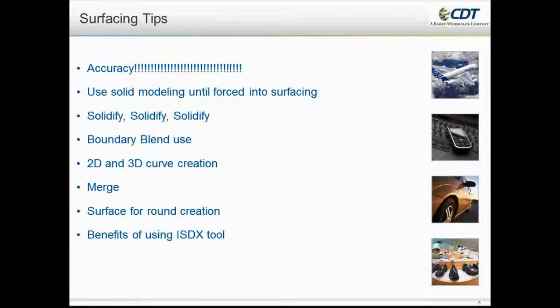I was a victim of this when I did a lot of design work in my past jobs. I would do all my models in surfacing, and my model trees couldn't be scrolled through. They would be nothing but curves and merges and surfaces and solidifies and merges and more surfaces and more curves, and these things would be forever. If I had sat back and looked at it, I probably could have done 25 to 30% of my features with solids, and then gone into my surfacing, and it would have been much easier to deal with.